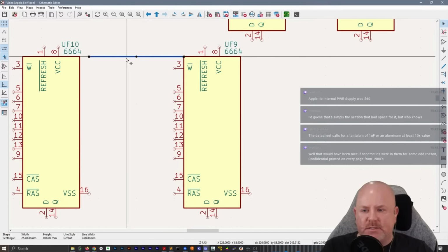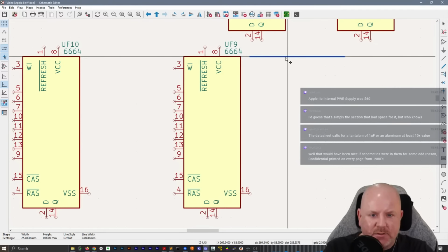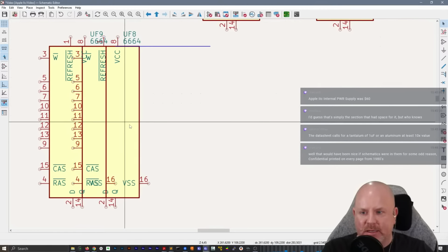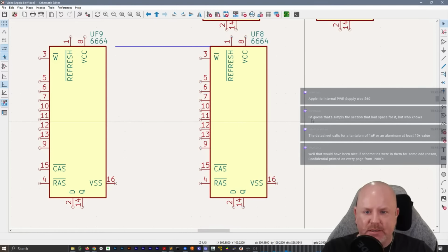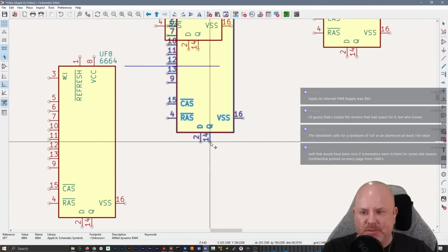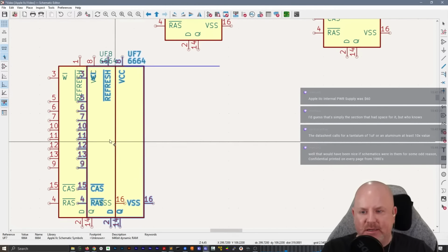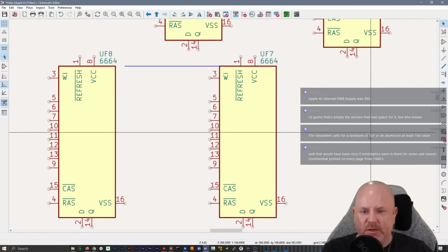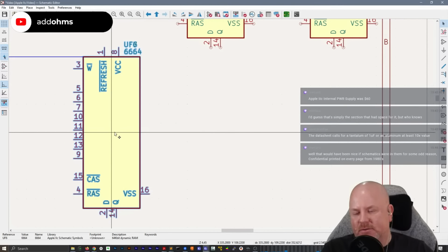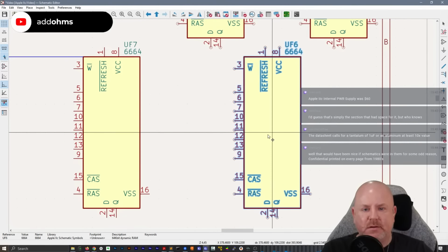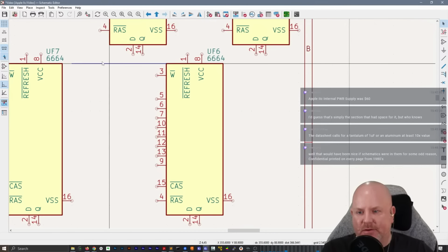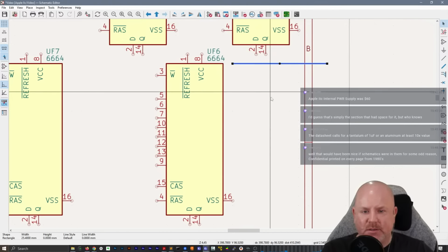There we go. There's something with the grid behavior, and I'm not sure I understand it yet. When you first pick the part up, it doesn't snap to the grid right away. But then the second time you handle it, it snaps into the grid. So it's almost like its default behavior is to stay on the original grid. I'm noticing that to hold things on a grid, you have to move it twice, which I think is weird.